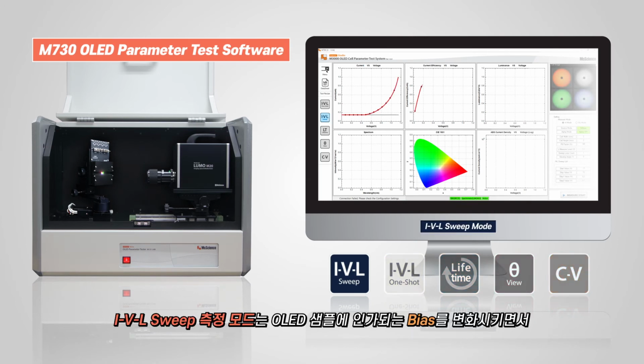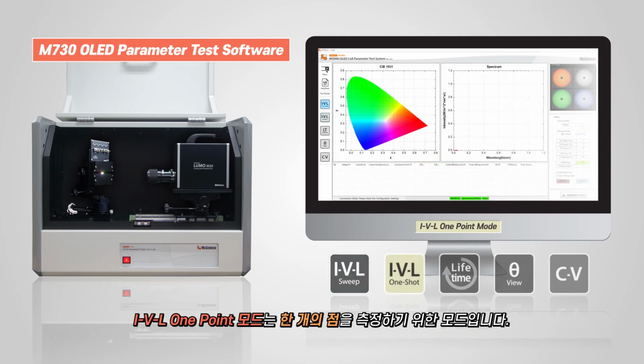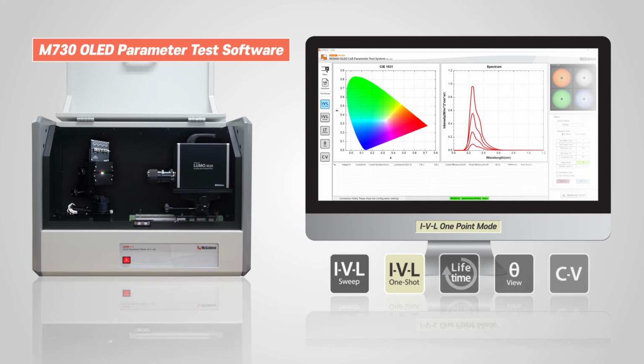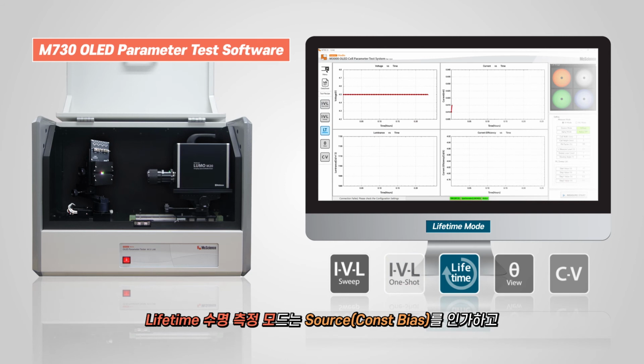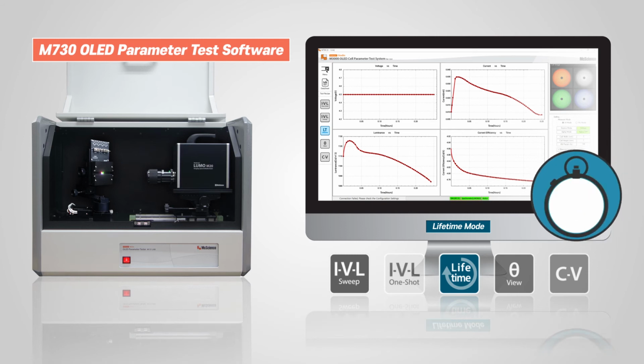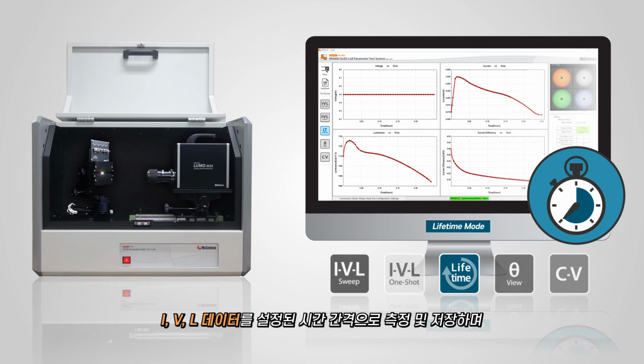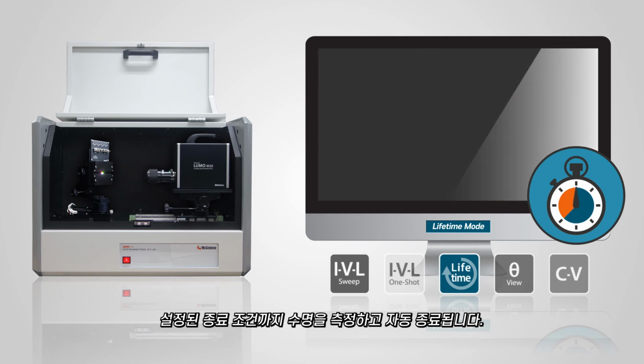IVL sweep mode sweeps the selected bias input range on the OLED sample under test, while measuring and recording the luminance data for each sweep point. IVL one-point mode is for measuring one data point. Lifetime measurement mode applies constant bias source to the sample under test, while measuring and recording the changing luminance data over time. This mode records the IVL data according to preset time interval, until the preset end condition is met, at which point the experiment ends automatically.